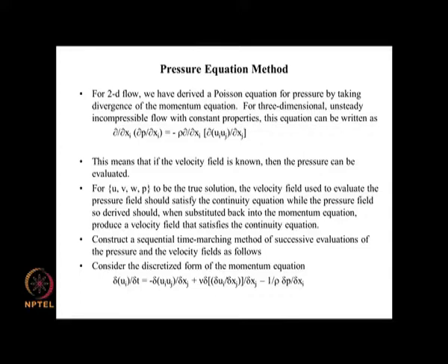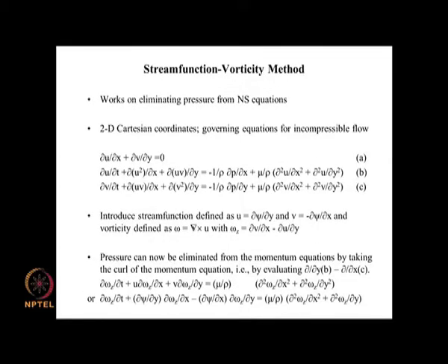So, the idea of the pressure equation method is already the germination is there in the stream function vorticity method, where we derived an equation for pressure. So, we look at a method which is applicable both for time dependent flows and 3-dimensional flows at the same time. It is not either for this or for that.